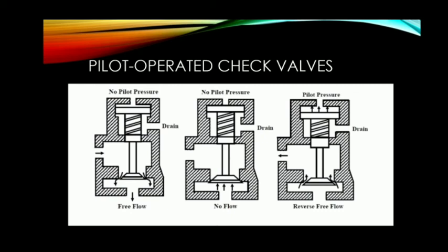They also are used to support vertical pistons which otherwise might drift downward due to leakage past the directional valve spool. With no pilot pressure, the valve functions as a normal check valve. Flow to the bottom is permitted but the reverse is blocked. If pilot pressure is applied, the valve is open at all times, and flow is allowed freely in both directions.